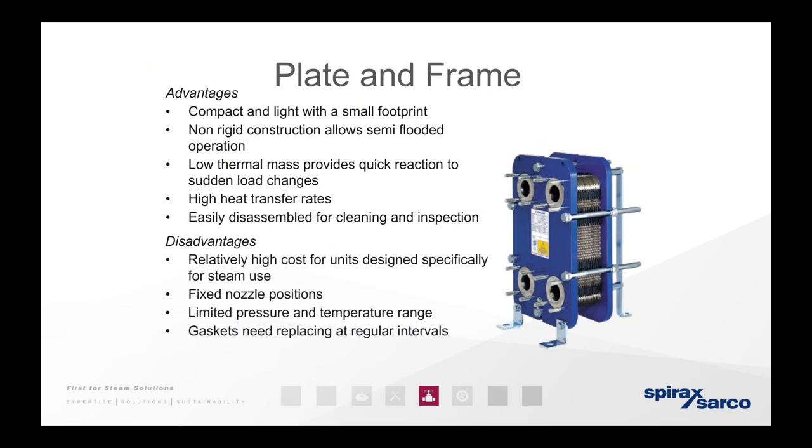Disadvantages, so they're quite high cost in comparison to other solutions in the market. Fixed nozzle positions, so you can't move anything on there. Limited pressure and temperature range, because as we said, these will only go up to about 10 bar, slightly over on some units, but not by much. And gaskets need replacing at regular intervals.